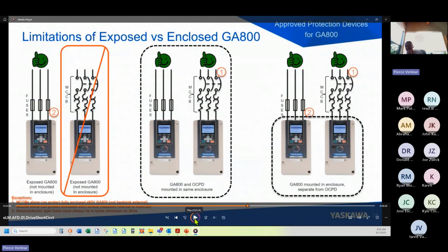I want to point out something here because a lot of customers do buy the drive and the NEMA 1 kit, which is the sheet metal that mounts below the drive in some of the larger VFD ratings, to achieve an IP20 or basically prevent people from touching the power conductors. And if you can see my cursor here, the NEMA 1 kit's typically located down below the drive because our input and output power conductors are located always on the bottom of the drive. Note that if you are mounting this thing